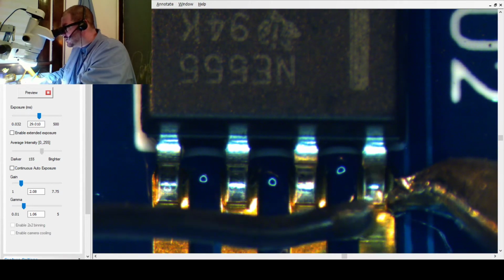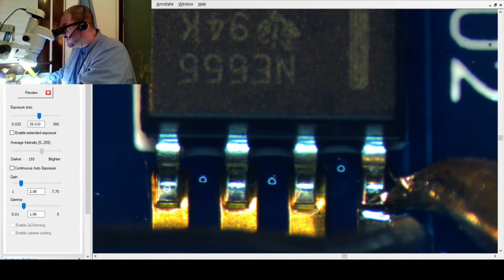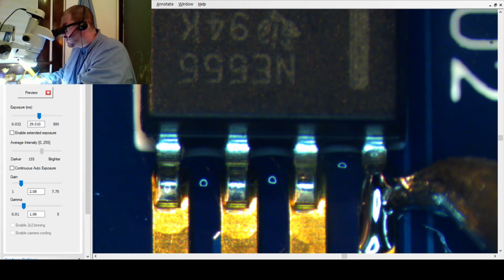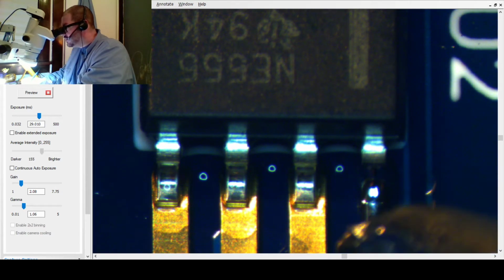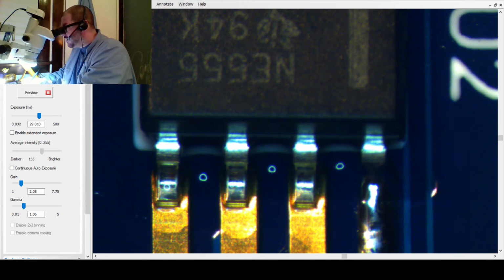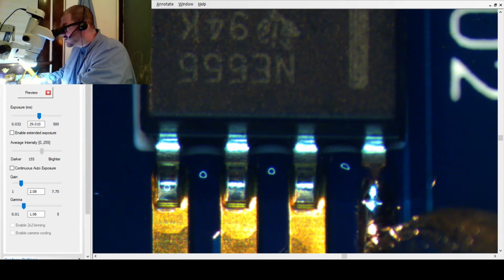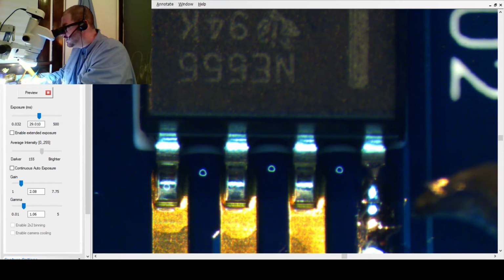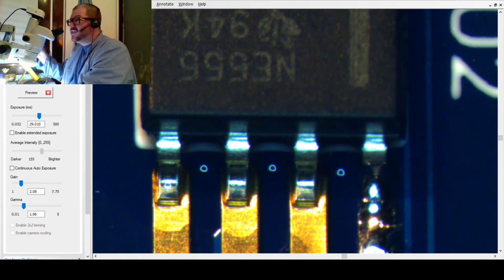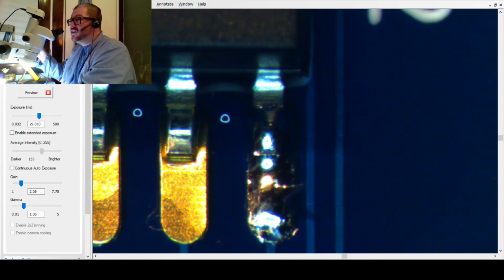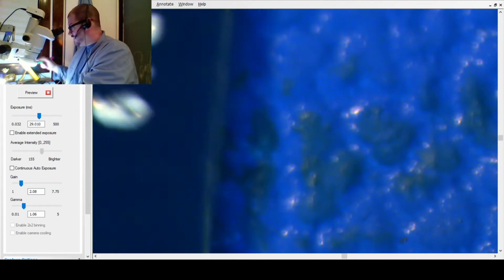Now watch this as the solder just creeps up both the side of the part as well as onto the overall pad itself. The solder is actually attracted to both the leg of the part as well. But you'll notice that as I continue to move this around, see that? You see that guy right there? That is bad. That is not what I want. You see this thing that's hanging loose? That's probably hard to see.